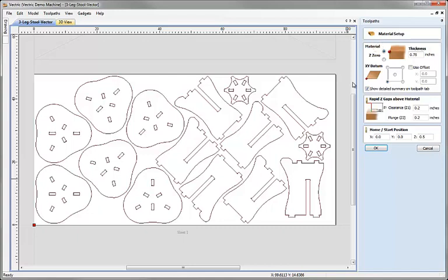In this case, the part that we're cutting is going to be machined out of the material. So what's very important to us is that the tool is going to cut through the material. So there may be some benefit in this case, in order to avoid the fact that the material may not be a consistent thickness, of choosing the Z0 to be off the table rather than being off the top of the material. What's helpful about this is I know that if I'm reference off the top of the table when I set up my machine, that's going to be dead on 0, and so if the tool is coming down to a value of 0, then that will be at that surface position.